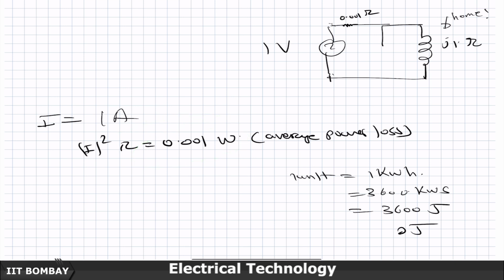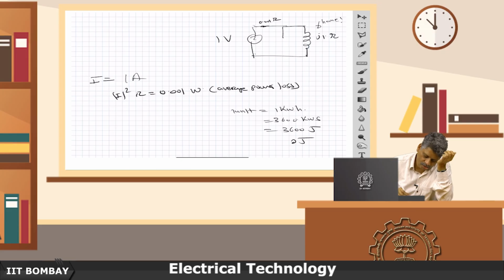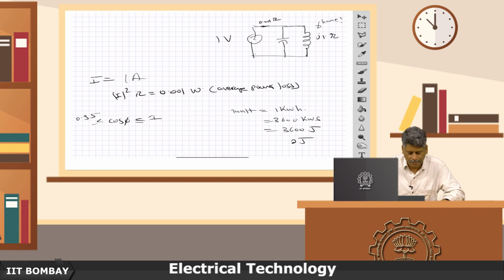It's in the business of transportation, it's not, so it's also not going to pay for it. So what is done to handle this kind of situation is that distribution companies, typically for large loads, enforce that the power factor should be held within a tight band, let us say 0.95 to 1.